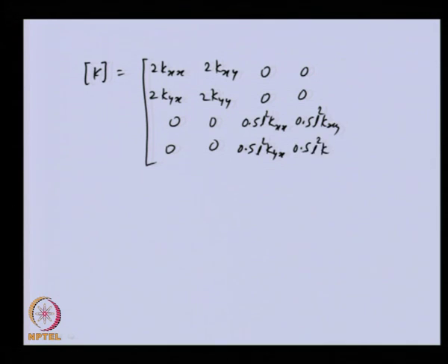These cross coupled terms were not there earlier, only direct stiffness terms were there. In the previous lecture, we had these diagonal terms. Now these off diagonal terms are coming into the picture. Because they are getting multiplied by the linear or translatory displacements, they are coupling the motion in 2 directions, and these are coupling the tilting motion in 2 directions,